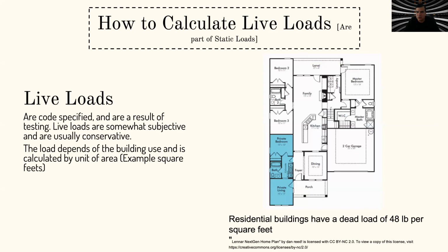Why? Because we're not sure exactly what the weight of the elements in a building will be. Live loads are everything inside of the building that is not fixed, including the people, the furniture, and some of the equipment that is not fixed. Well, it's just something very subjective and very conservative. It's just a particular weight per square foot.